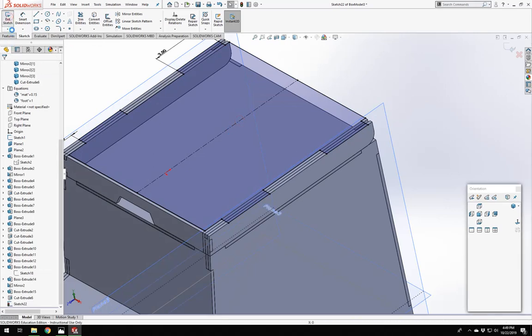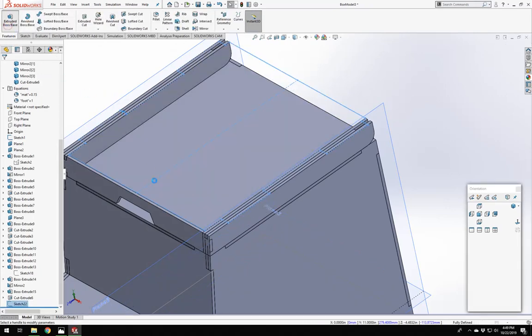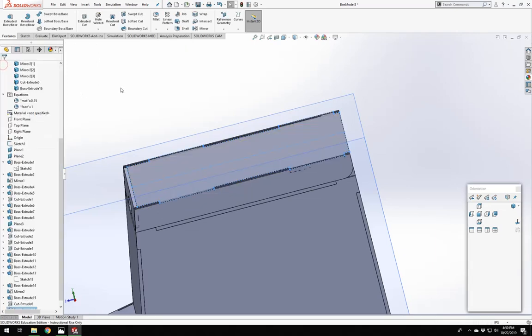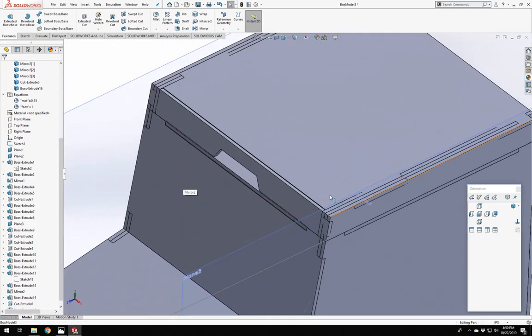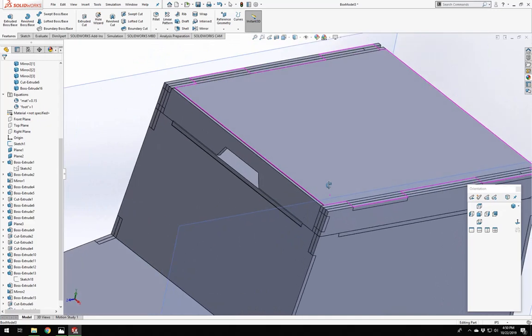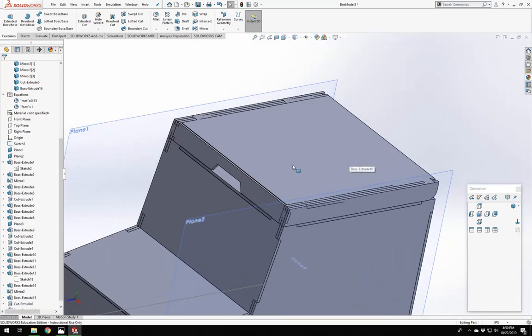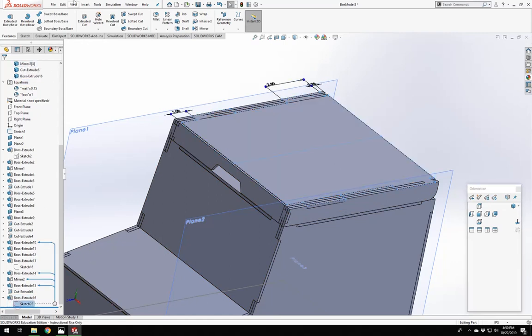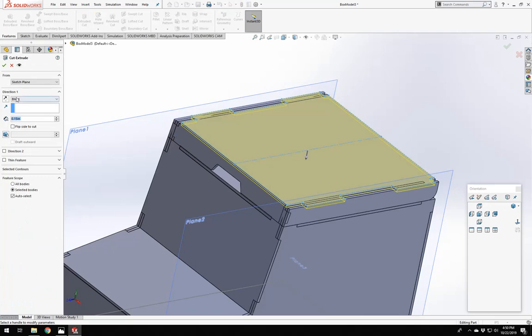All right. So now we can do extrude with this, other direction, our material thickness, and we're good there. So in order to do the cutouts for these, there are actually a couple ways we could do this. One easy way, say for this one, is we can just select this sketch again and say extrude cut and is equal to material thickness. And it's going down, which is what we want.